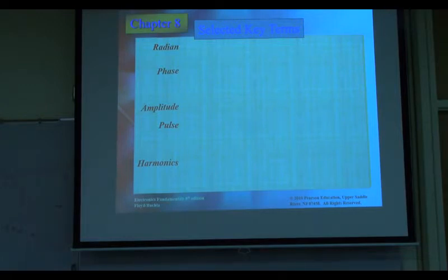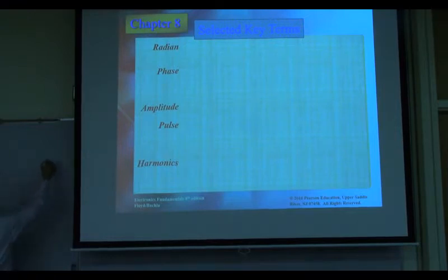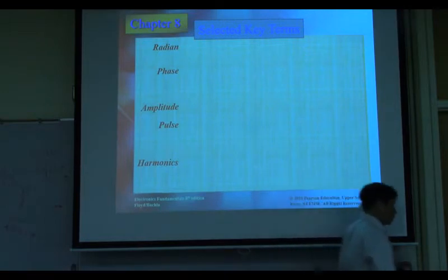Phase, what is the phase? Mathematically, phase is only the angle. Sine of something, 30 degrees, so that is the angle. But in electrical engineering, the whole part, 377 times time plus the angle, is the phase. In math, we said this is sine of 60 degrees, that is the angle, right? And this whole argument here, in radians or degrees, no matter what, is called the phase. The phase actually is relative to a reference.